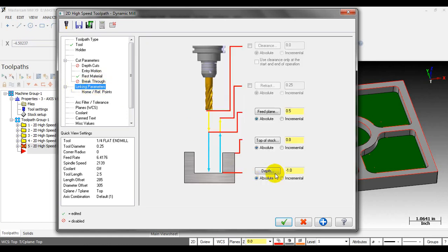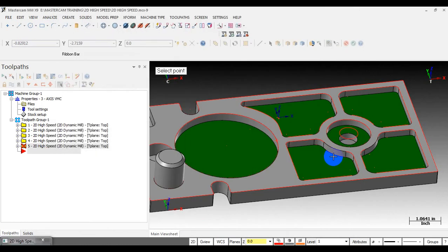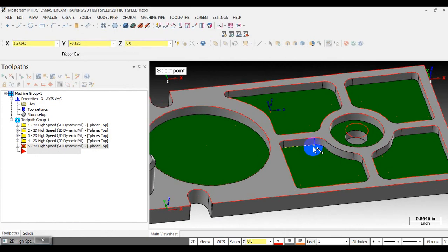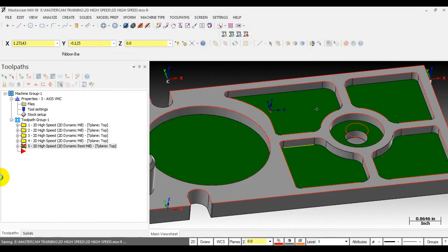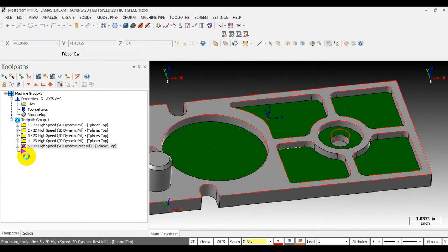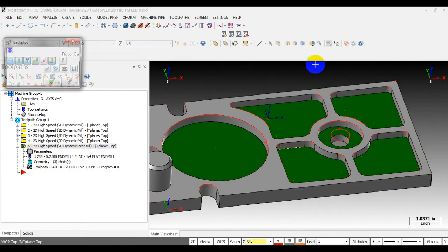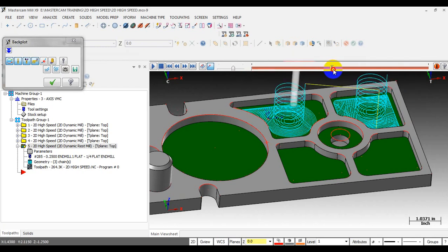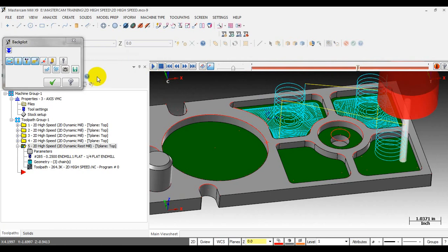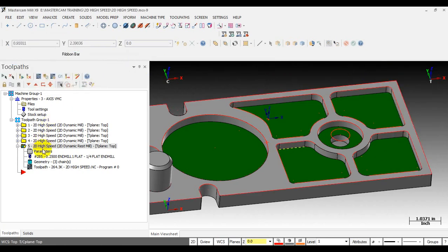Okay, that's all for the toolpath. You check the linking parameters to make sure you select the right depth for the operation. Okay, and pick a distance point. Okay, click OK. And wait a few seconds. Ooh, what happened here? Mastercam, oh, you can see here there's some problem. Mastercam machines the entire pocket, not just the rest material. I will check for the reason.